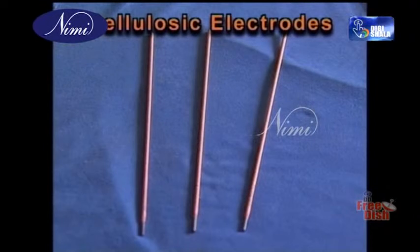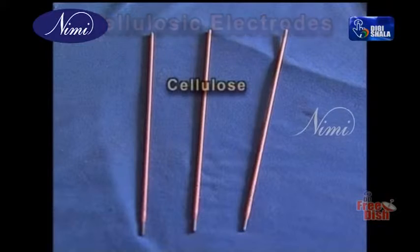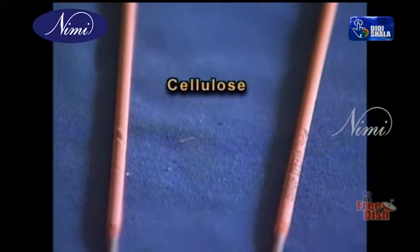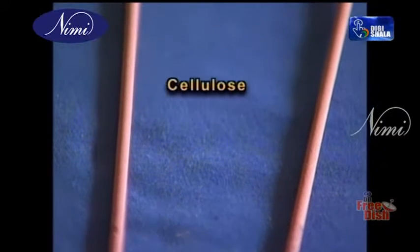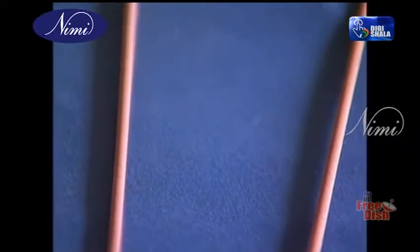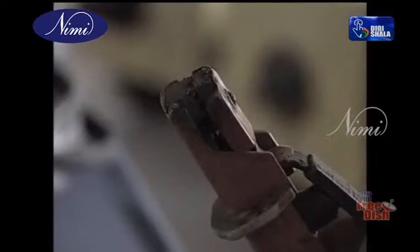Cellulosic electrode coatings are made up of materials containing cellulose, such as wood pulp and flour. The coating on these electrodes is very thin, and the slag is easily removed from deposited welds. The coating produces high levels of hydrogen and is therefore not suitable for high-strength steels.